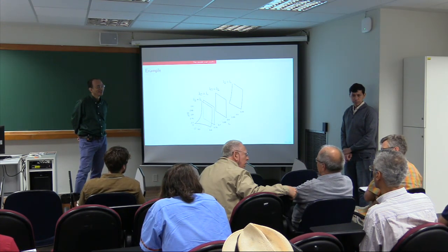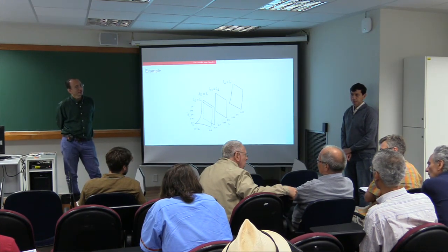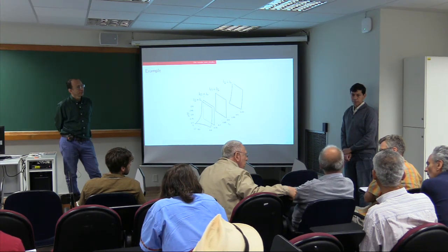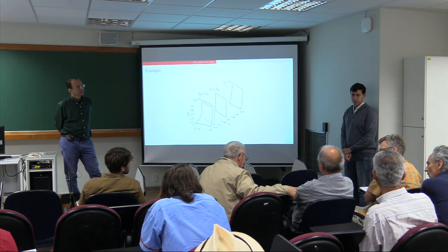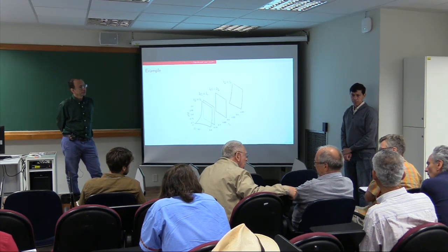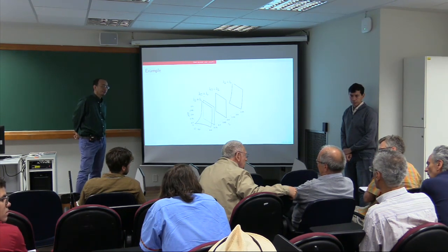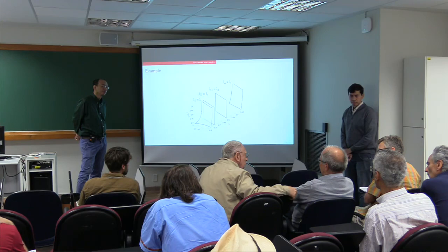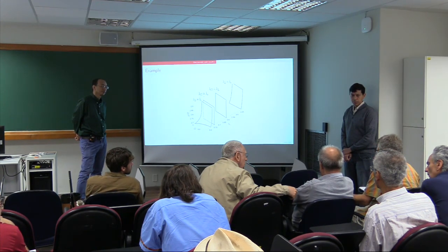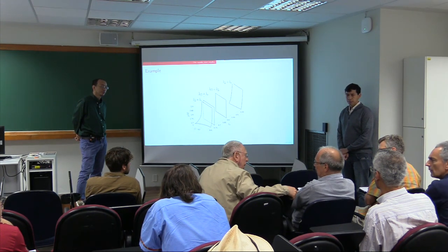The occurrence of elliptic regions means that the models have a fault, in the sense that the way we try to define relative permeabilities empirically is not right in a fundamental sense. Sometimes we can circumvent it, but if we cannot, something is wrong with the model. I know many people disagree with this. Very much. I agree.